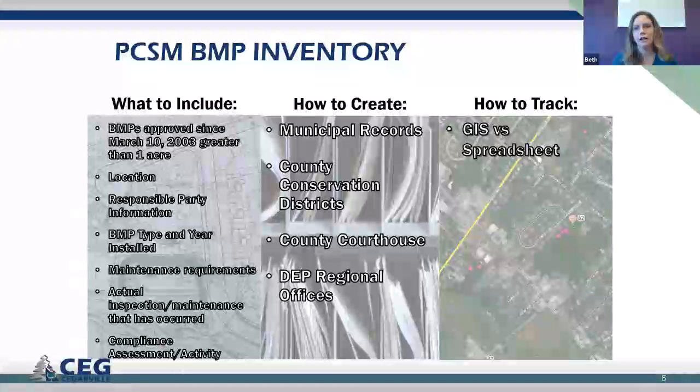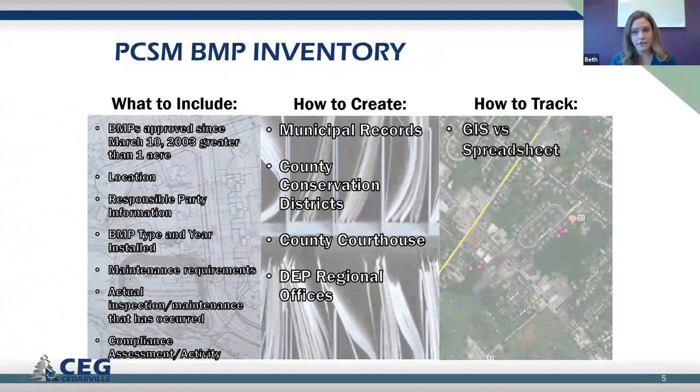And then when it comes to getting the plans, that's another consideration. Sometimes municipal records aren't comprehensive. Sometimes that information went with a previous consultant, or it may not be in-house, or maybe you can't find the latest and greatest. The County Conservation District can also be a good resource for that. The courthouse is also a good resource for that. However, a lot of times they don't record the entire land development plan set, so you might not get the post-construction stormwater plans.